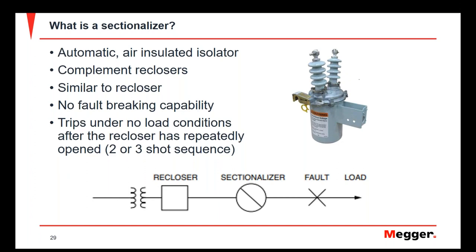And as we discussed earlier in the presentation, these DC high-speed circuit breakers are unique in their opening speed whenever there is a fault condition. However, they only have an instantaneous trip function. They don't operate in the same manner as the low voltage circuit breakers that we talked about, which have different protective functions such as long time, short time, and additional ground fault protection of the circuit.